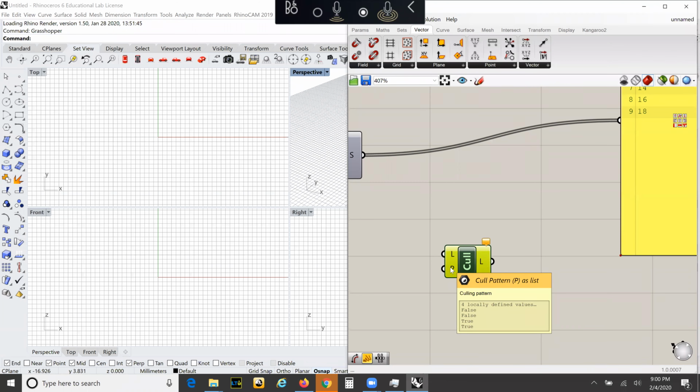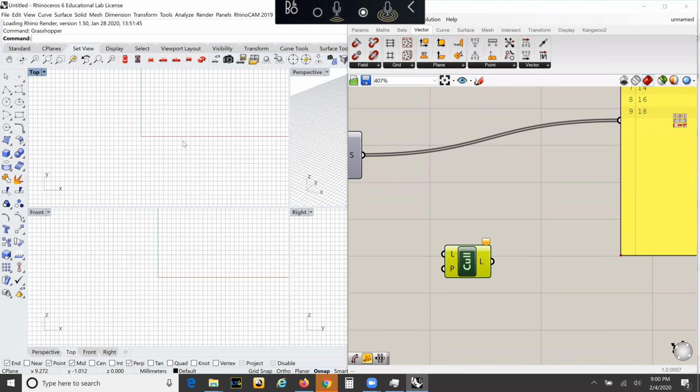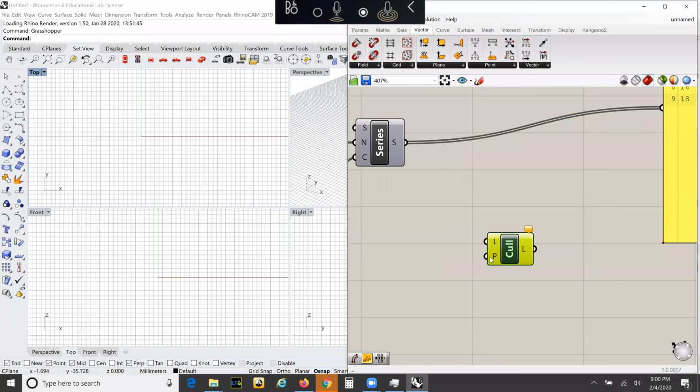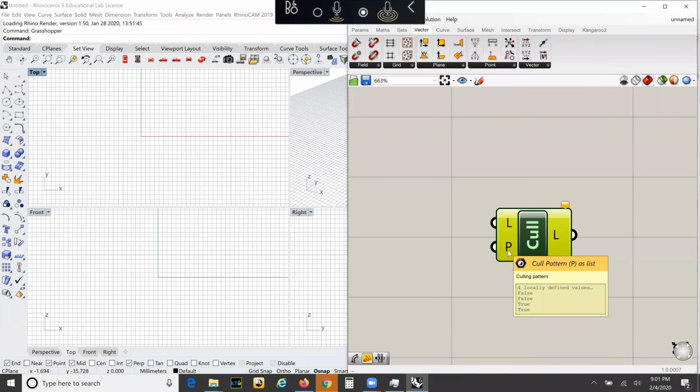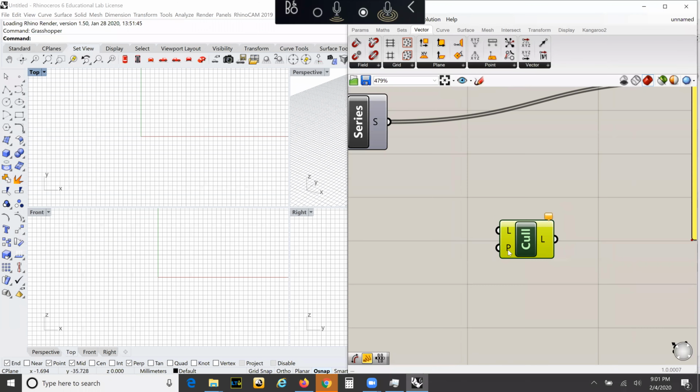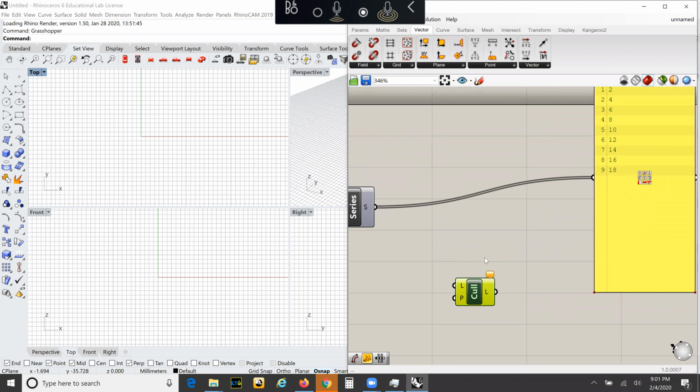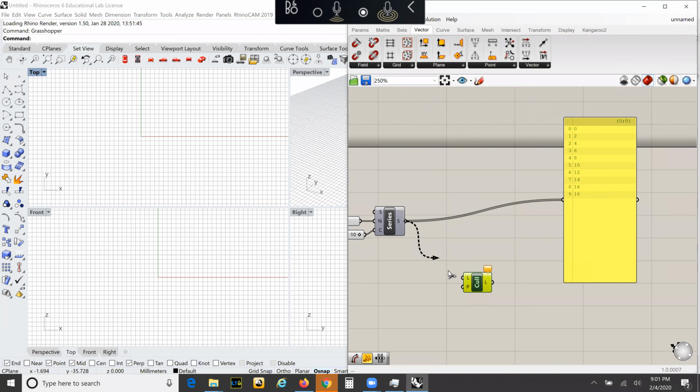A Boolean statement is different from Boolean in Rhino. In Rhino, when you think of Boolean, you think I'm editing geometry, removing geometry, or Boolean union. It's a completely different meaning in programming. Boolean statements are true-false statements. The default is false, false, true, true. So it's going to remove 2, keep 2, remove 2, keep 2.